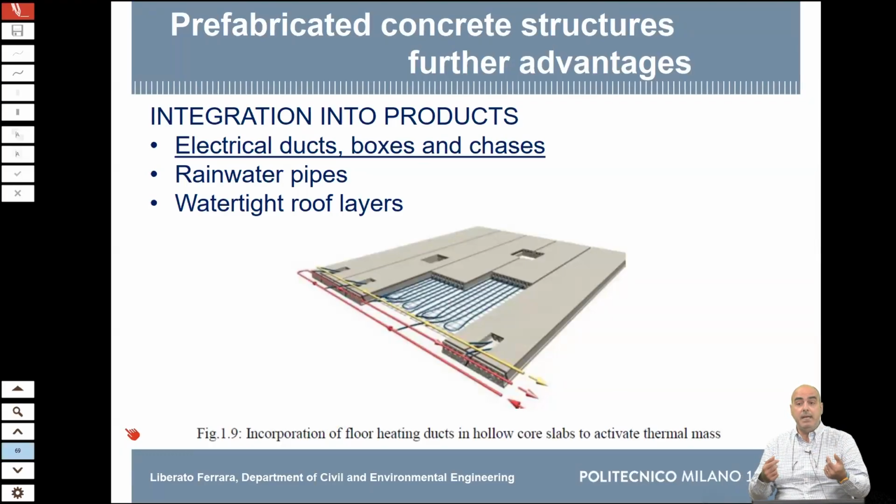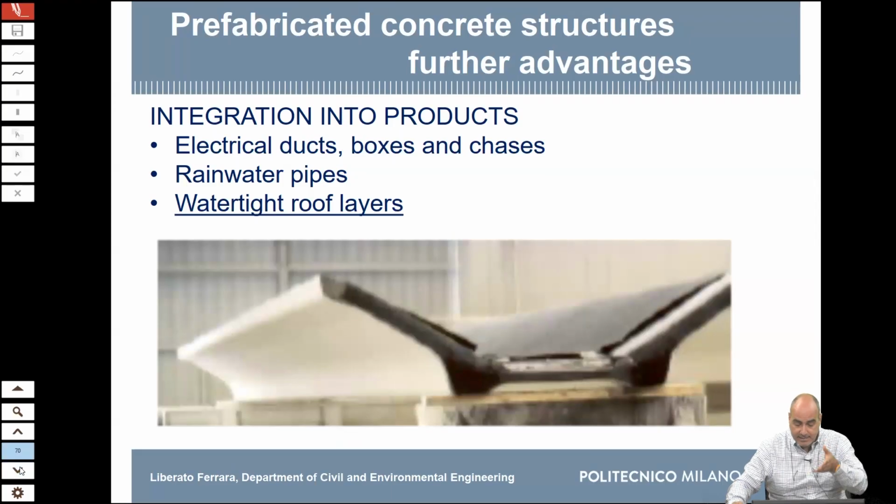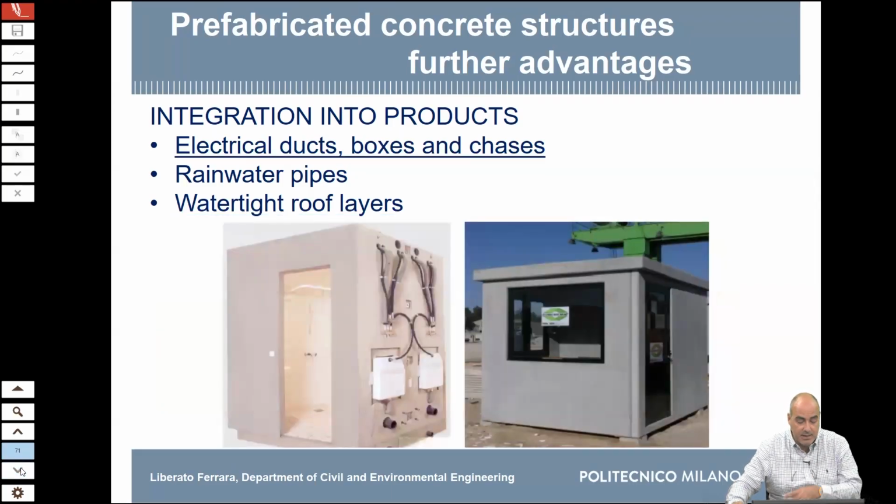This is in industrial buildings, but in residential buildings, you can bring floor elements which already have some piping, some ducts, some electrical installations and so on. For example, hollow core slabs are naturally prone to this because they already have these cavities where you can accommodate them, but you can also have these fixings already installed in the elements when they are prefabricated and bring a partially or quasi-finished element to the job site. These are some images of the waterproof layer for these elements, and these are images of modules of an apartment building. This was a bathroom which comes with all the equipment already installed, and brings, say, 96 apartments in 96 days. You have to offset most of the work that you can so that you limit the work on site. And I think this was the last slide for this morning.